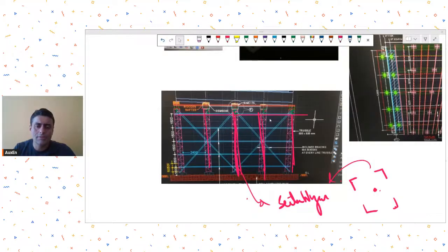Although this trestle system is a temporary structure, as per IS 875 Part 3 2015, they do require us to consider wind loads for temporary systems also. So you could consider temporary loads, consider the load coming from the deck slab, take the impact loads, etc. Find out the moments, axial loads, whatever, and then design your trestle and this entire system.